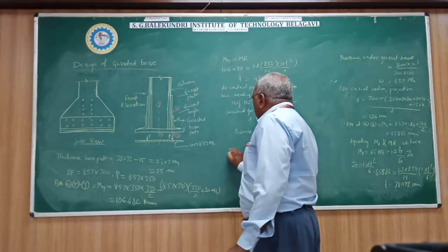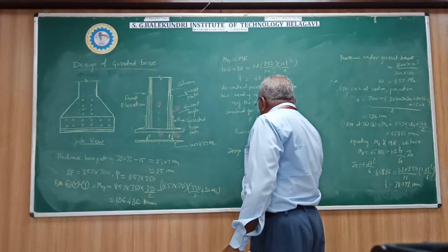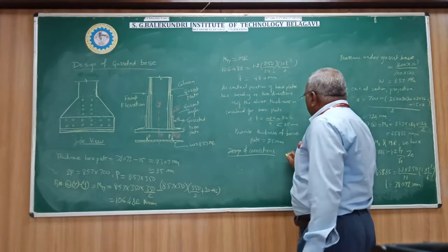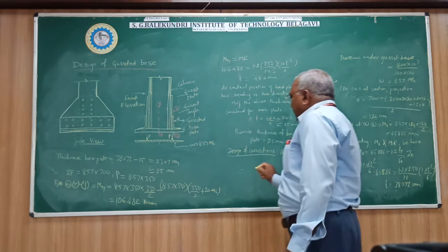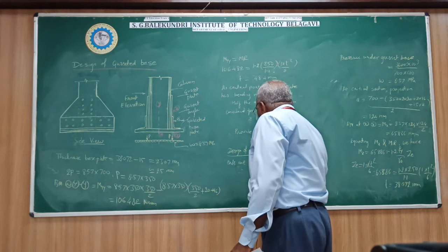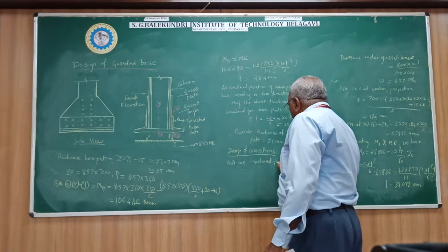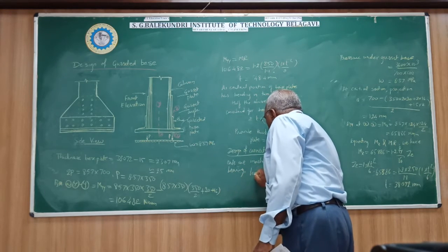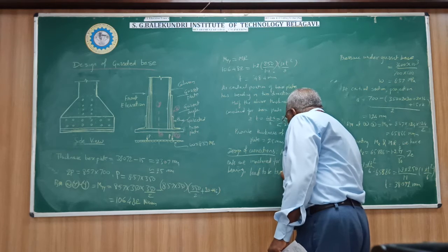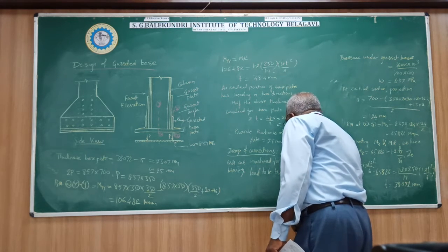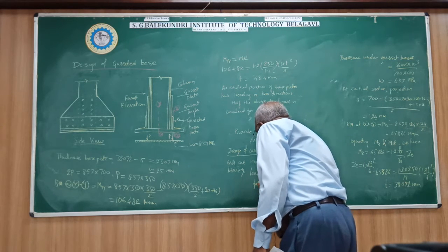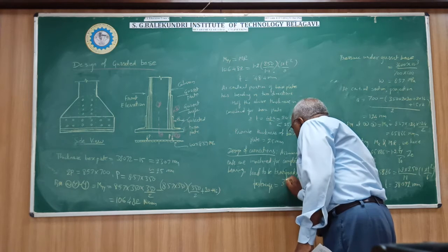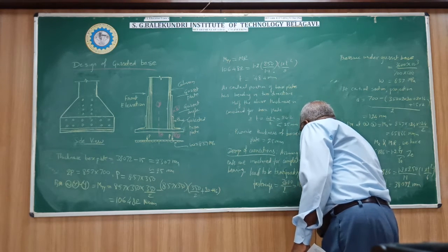Okay. So now design of the connections. That is how many bolts are required to connect the gusset angle and the gusset plate. Assuming ends are machined for a complete bearing, then the load to be transferred by fastenings equal to half the axial load, that is 3600 divided by 2, so it is equal to 1800 kilonewtons.